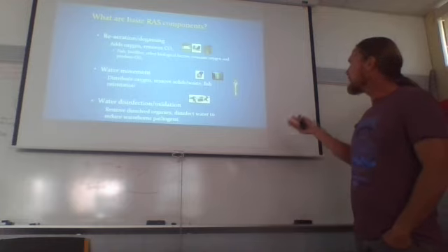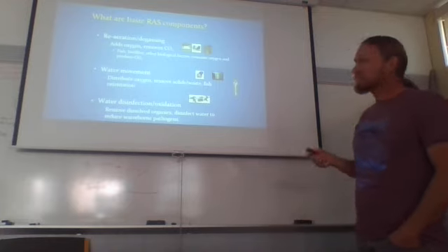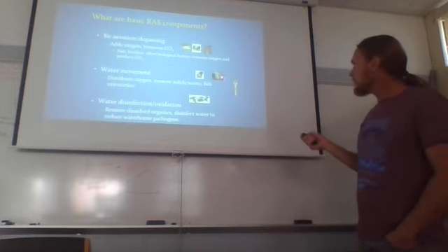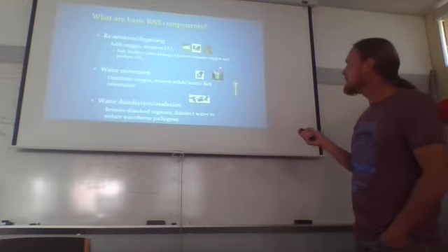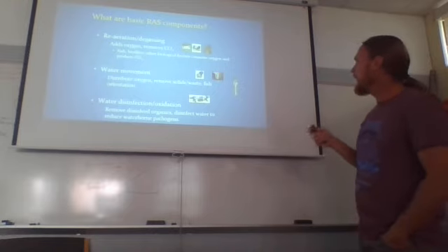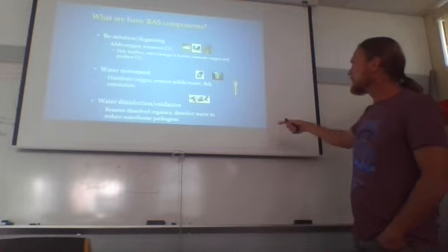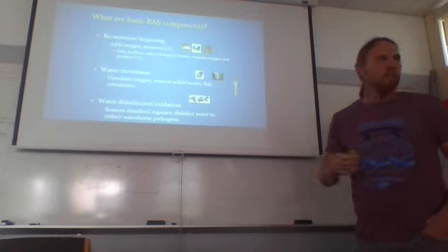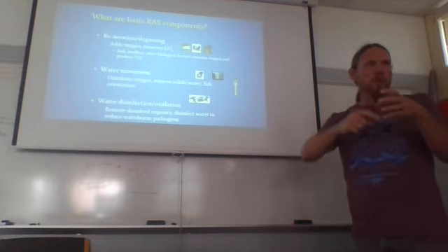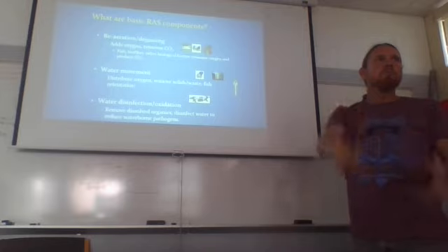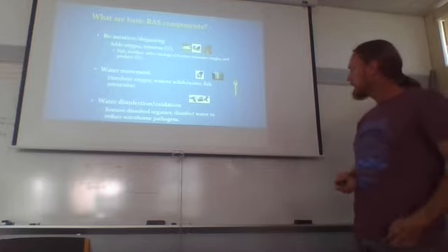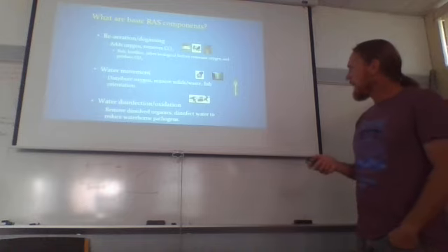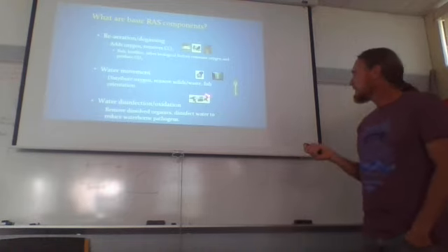Sometimes we add additional water movement devices besides just the flow of the pumps. Another thing you can do is using, I think this is an airlift device here, so without having to add additional circulation between the tank and the filter, you can create an airlift situation with an external pipe, an air stone in it, the air is lifting water up and creating a flow, aside from just an air stone sitting on the bottom.